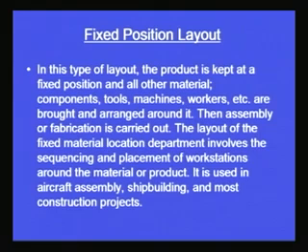Now where is it used? Let us try to understand it this way. We have a very huge and large product which cannot be moved from one place to another. So we are locating it centrally at a particular place where all the other machines, equipment, and manpower can be brought, and they can do the operations or the assembly operations on that product at a fixed position only.